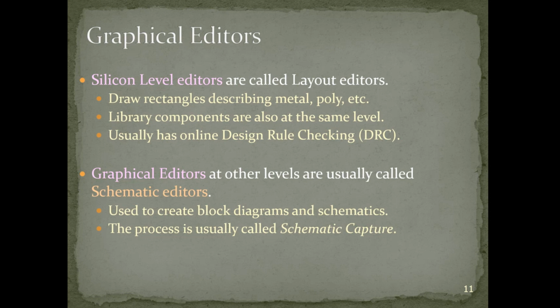Generally speaking, that could be a fairly tedious process, so this tends not to be quite as efficient as programming in VHDL. Generally speaking, programming in VHDL would tend to be quicker at doing this sort of thing. But sometimes mixing and matching can be very useful. And we will be covering this sort of example in practical sessions as well, just to see how the Xilinx software, for example, allows us to mix schematic with VHDL as well, which is quite handy.